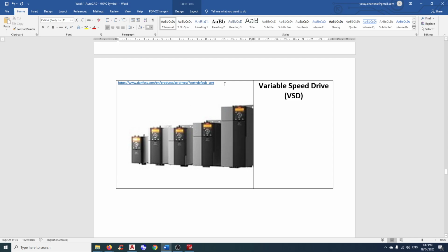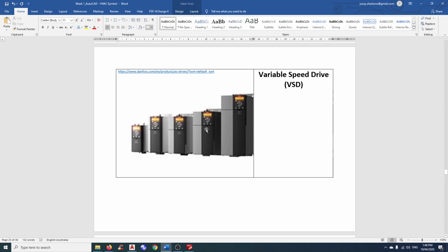And if the room is not occupied, just to maintain the freshness, the air change rate into the room, we can run the fan at 30%, hence saving energy. In the old days, we always ran the fan at 100%, consuming 100% of the energy all the time.